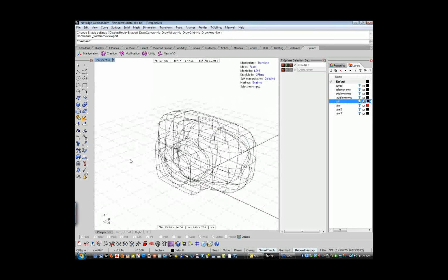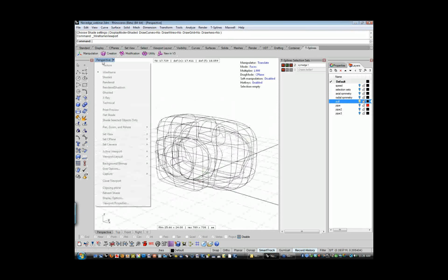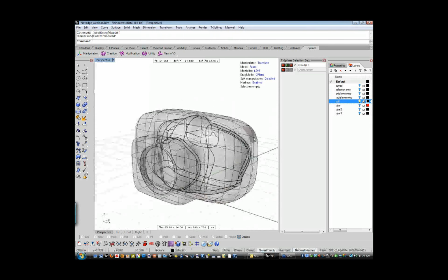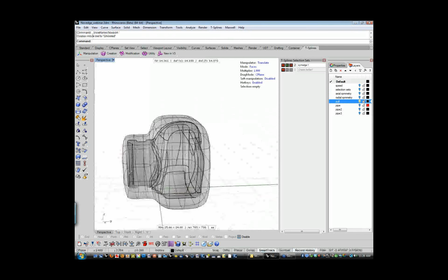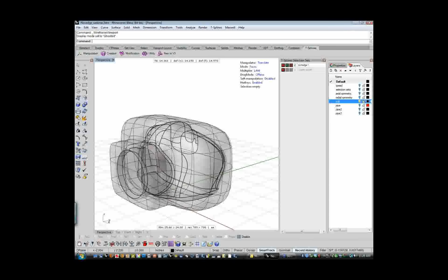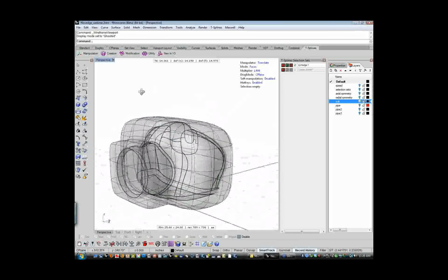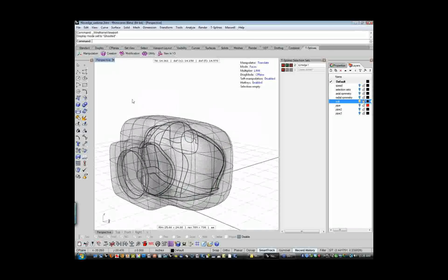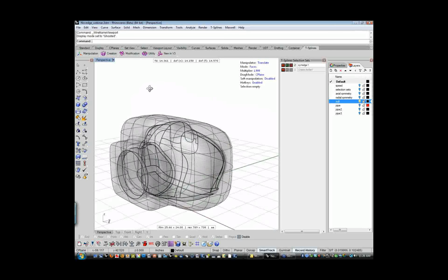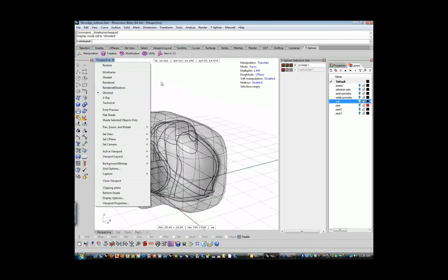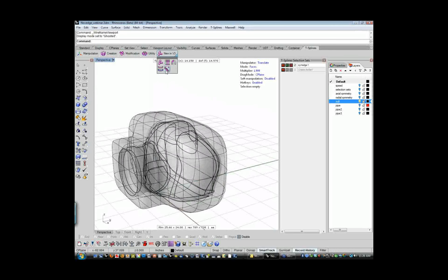Basically, what I'm showing here is the pull tool, and what this allows you to do is to take an object. I don't know if you can see this, but let me ghost the view here. I have a polysurface model, a Rhino camera model. This is all just Rhino polysurfaces joined, and then I have a T-Splines model over the outside of it. Basically, I'm going to vac form this T-Splines object over the NURBS object to use that as a starting point for further refinement. So let's go ahead and run this tool, and hopefully it's going to behave itself.